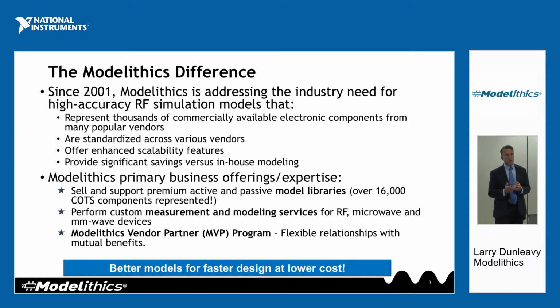Another thing that's different is that, say for passive components, the world without Modelithics is a world where you go to many different vendors' websites and you can get an S parameter file. The S parameter file is valid basically on the test fixture, substrate, and solder pad footprint that it was used to make the measurement. So it's really just a snapshot. In contrast, our models are scalable in terms of the substrate, solder pad dimensions, and part values, so you can optimize and tune them, taking into account the circuit environment that you want to work in. And of course, you could develop these models yourself, but if you're a circuit designer, that's kind of a distraction from your design flow process.